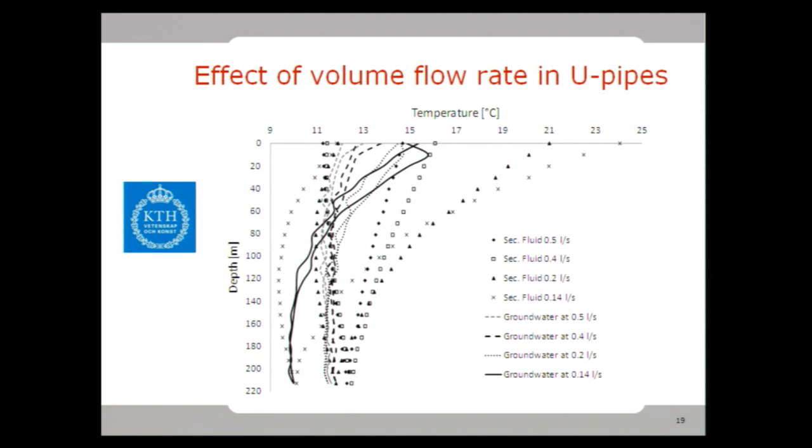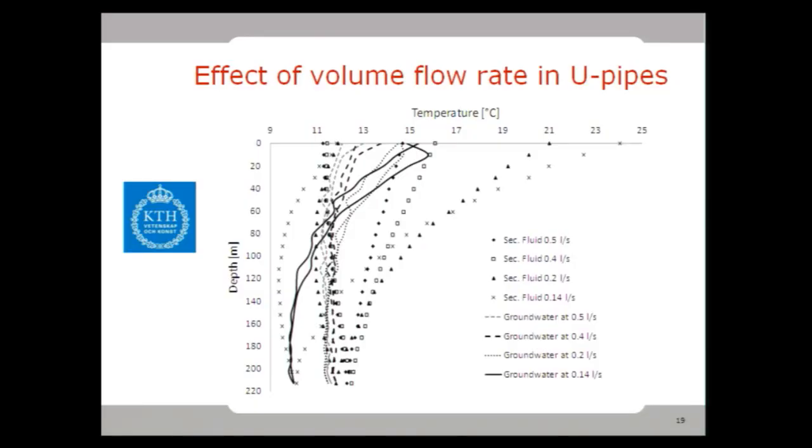Going forward into the second heat exchanger tested here, I have done a thermal response test with fixed heat injection during a period of time where I imposed different flow rates. And here you see the fluid temperature profile as well as the groundwater temperature profile at these different conditions. And you can see the dependence on the flow rate for a given heat rate.